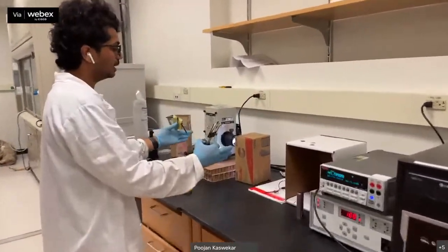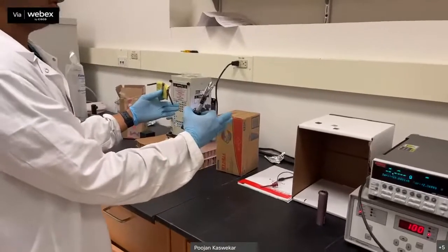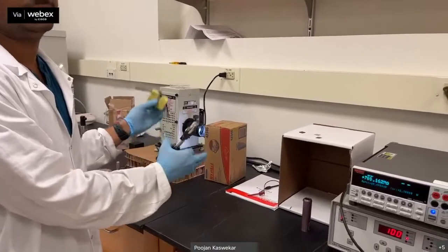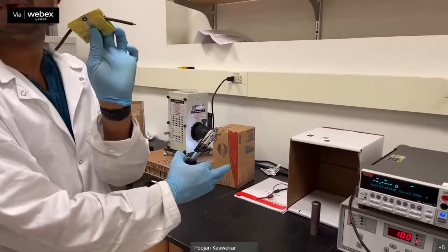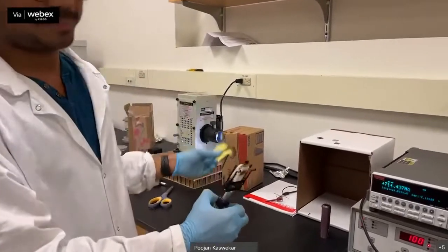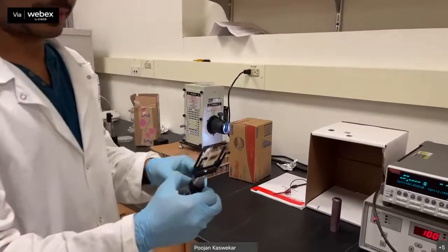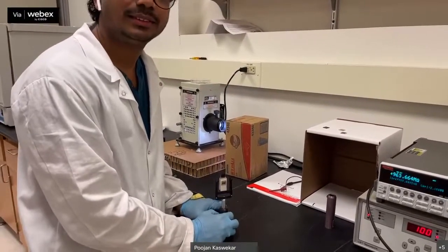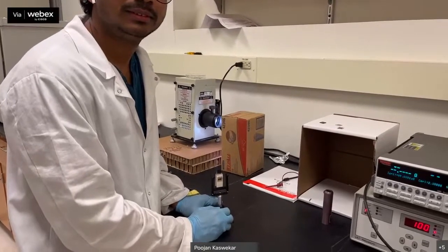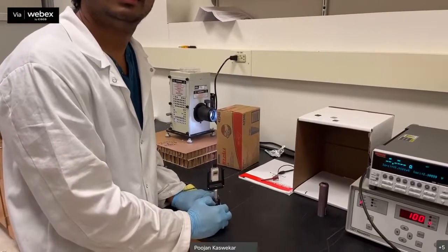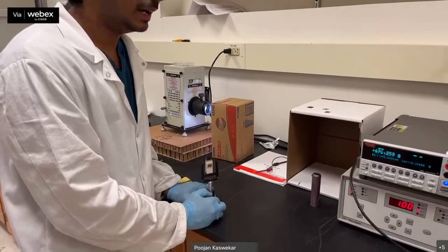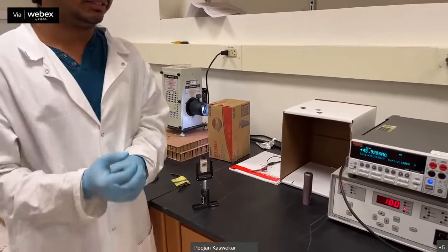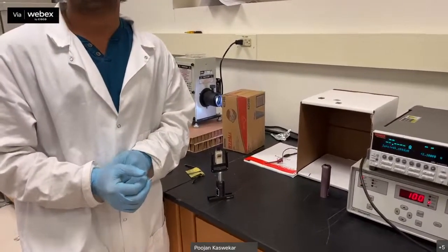The distance between the cell and the source optimizes our one sun illumination. When you have one sun illumination, this typical device is going to give you 1.64 milliamps of current. So you can vary that intensity by changing the distance between the source and the substrate, the device. Yes, you can typically change that one, but normally we do IV calibration with one sun illumination.